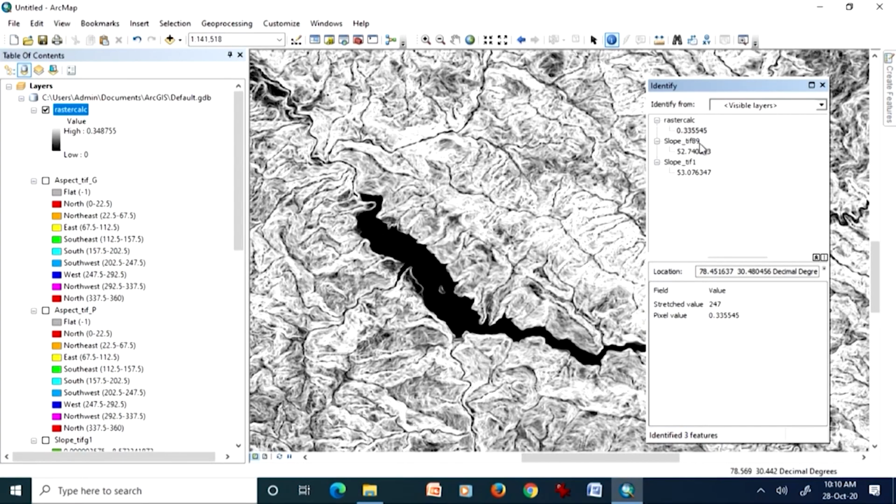If I choose Z factor 0.89, whether it is the planar method or any other method, I get more accurate values. So it convinces us that care should be taken about the Z factor, that is, the XY scale should be equal to the Z scale, and this can be managed with the Z factor.